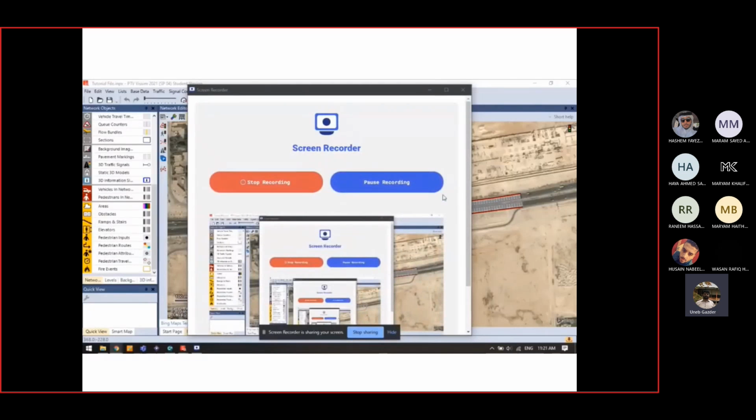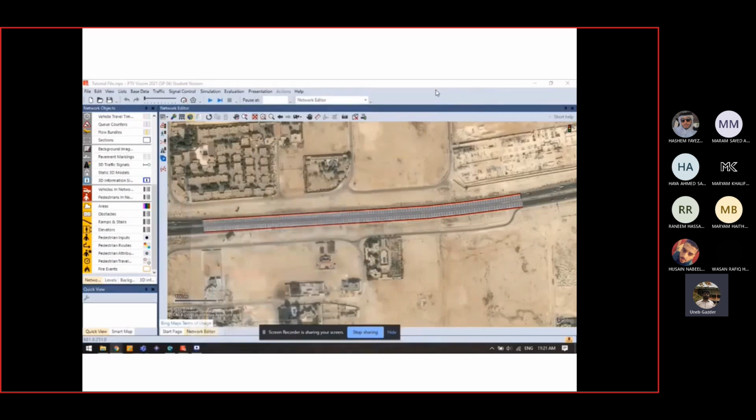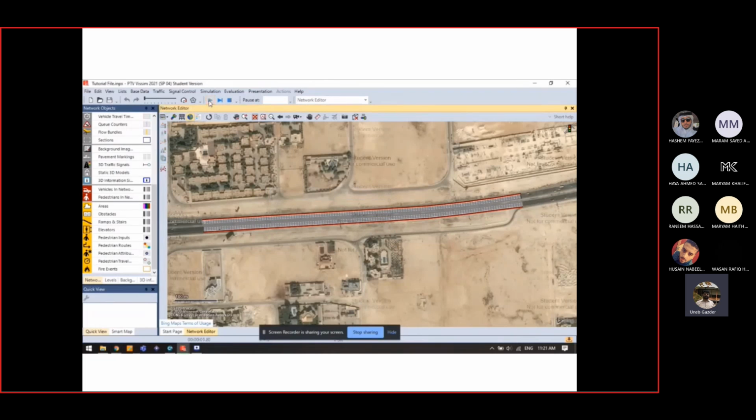Now we'll have a look at the different simulation parameters and how to change those and how to view the simulation in 3D and 2D. And then after that, we'll go on to using nodes and data collection points to actually determine the level of service, the speed of vehicles, and to count the vehicles. All the data that you can actually take physically from the highway, we can now take from the simulation that we've made. So to run the simulation, you go up to the play button in the top bar, hit play, and you can see the simulation running.